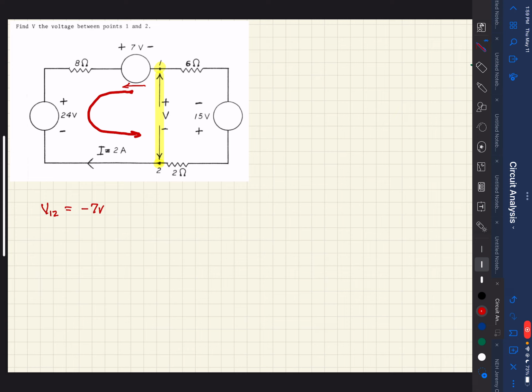So then we continue down this path, and when we do, we come to this resistor. Now we see the current here is given to us as traveling clockwise around the loop. So when it gets up to this point, the current's actually flowing that way. So it's against our direction that we're traveling. So again, that's going to be a negative.